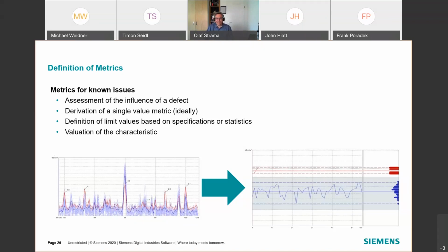But at the end, the roughness itself has no contribution to the velocity component of the vibration, so the laser is quite insensitive against it. It's more important that the reflection is high enough. So if it's a matte black surface, then it's difficult. But if it's die cast, gray cast, steel, whatever, then we usually have no problem.